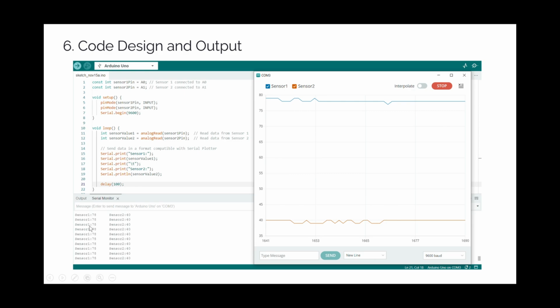Both sensors were successfully operational. During testing, we observed differences in the performance of the two sensors. Sensor 1 exhibits a high baseline and tends to report higher measurements. After detecting alcohol, its readings were slow to return to baseline. Sensor 2 had a lower baseline, more stable readings, and faster response and recovery times. Based on these observations, we select Sensor 2 as the primary component, with Sensor 1 serving as a secondary sensor.